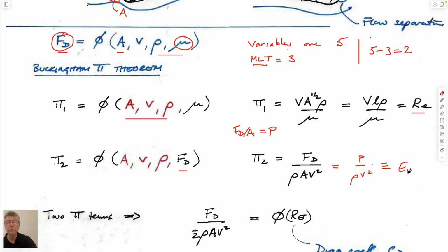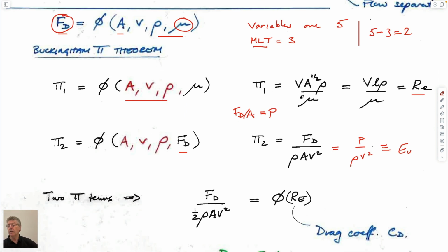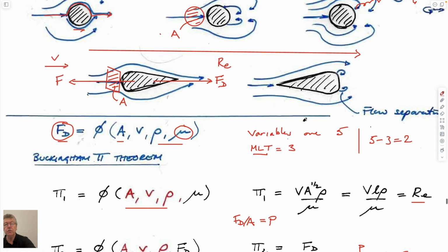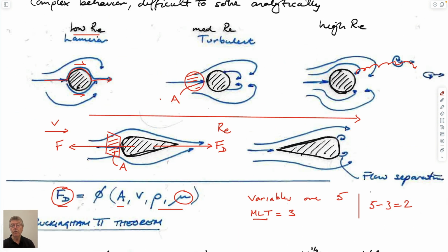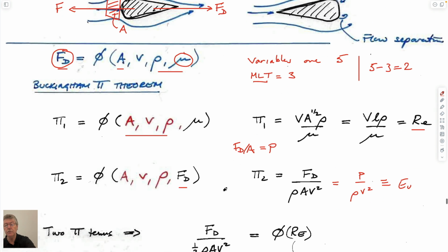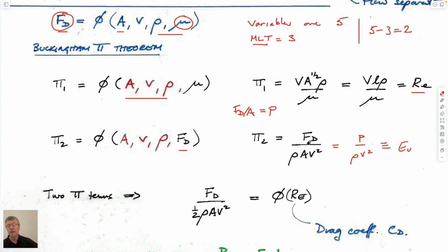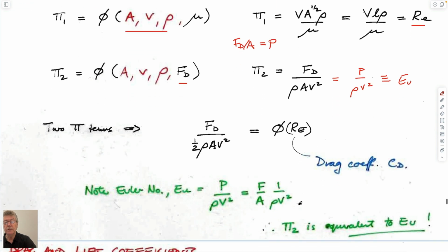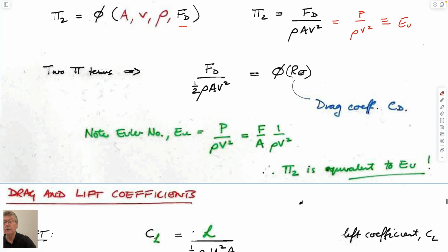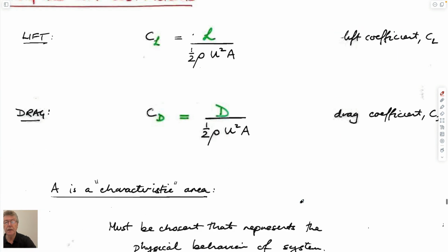So exactly what we knew before. We have to get the flow regime right, we have to have kinematic similitude, and if we do that, then we make sure that we're looking at the right flow regime where we are. We measure the pressures or forces applied to this structure. It could be the force, right, if we use this expression here. And from that, we can get an Euler number at that particular Reynolds number. And then we can use that to define lift and drag coefficients. So that's how it's done.